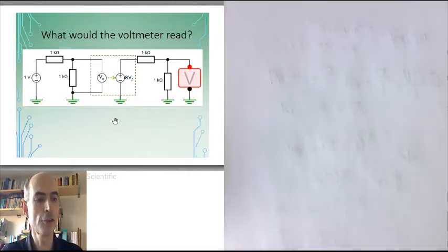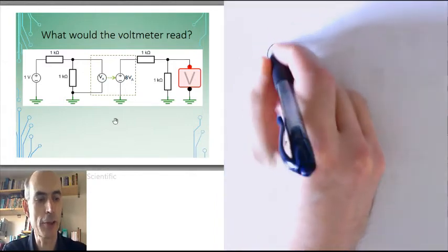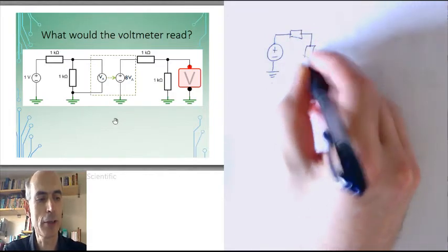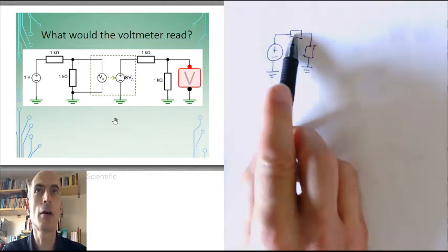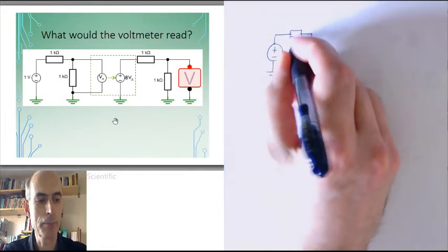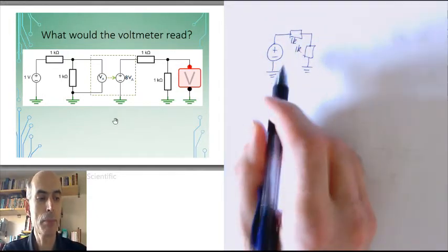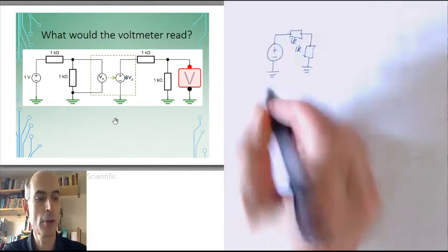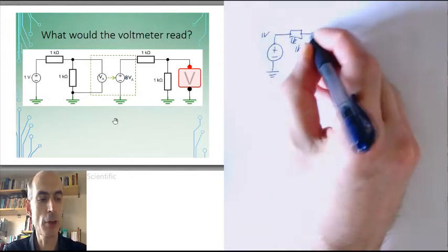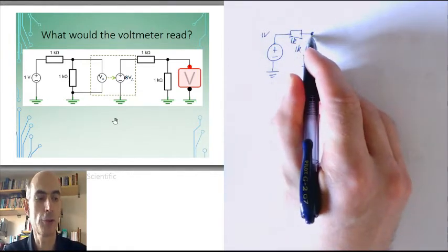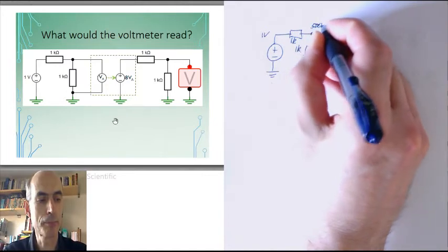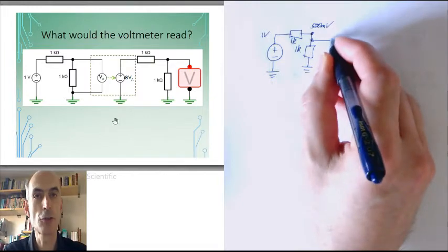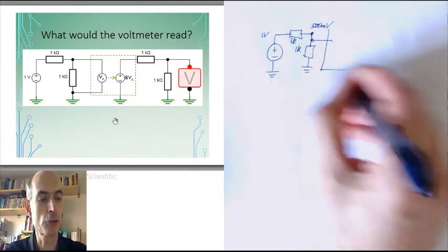2 volts because the first thing we've got in this circuit here is a potential divider. And it's a potential divider where both of the resistors are the same. They're both 1K. So, that means this potential divider will effectively halve the input voltage, which is 1 volt. That puts the voltage at this point in the circuit as half a volt, or 500 millivolts.